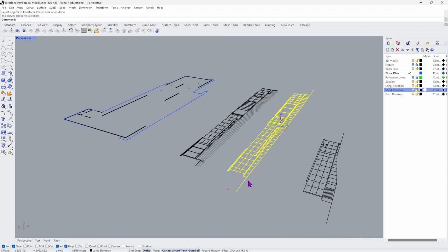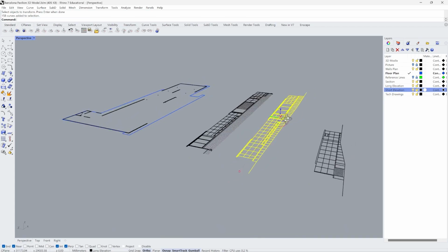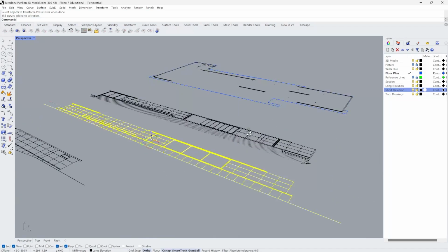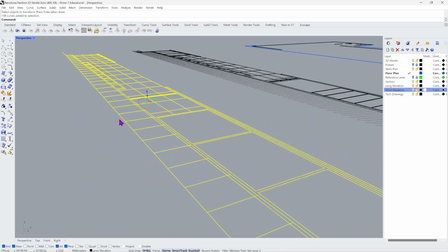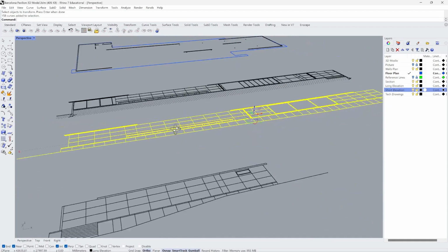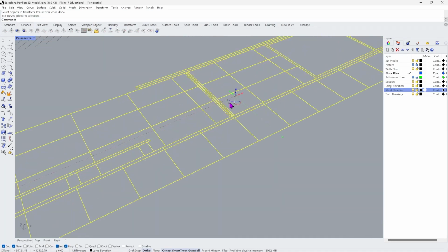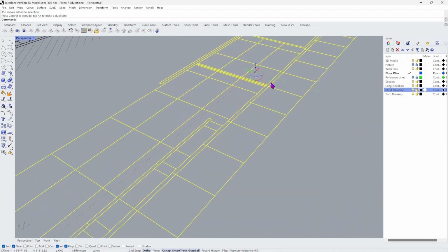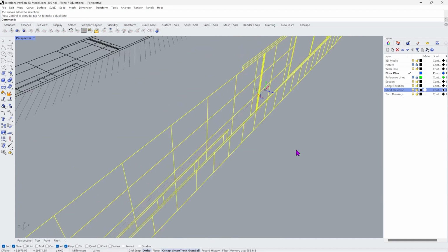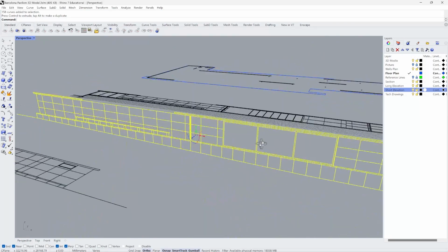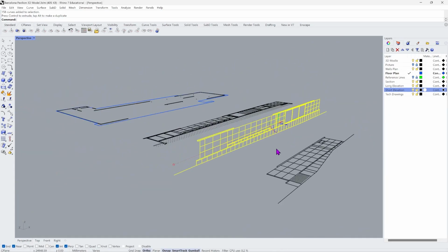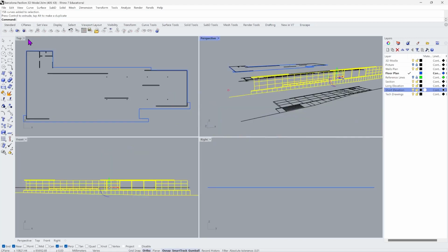I'm going to click on it, and I'm going to rotate it 90 degrees, so I want it to be standing up. For this task, Gumball is really useful. On the perspective view, you can see our Gumball has 3 arcs that allow us to rotate our object. In this situation, we need the red one. We want to put it vertically, so we click on the red arc once, type 90, press enter, and now our elevation has been set up vertically.